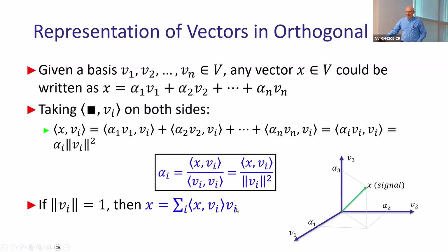Or we move from simple vectors to functions, and doing that for actual signals now. So this was kind of an introduction to how it works with regular vectors. But now, if you remember, we also defined an inner product for functions, which was the integral from 0 to T, or an interval A to B, whatever, of the first function times the conjugate of the second function, t being whatever the variable is, right? This was the idea of a generic inner product between two different functions. It's just the integral of the multiplication between them, in a sense.